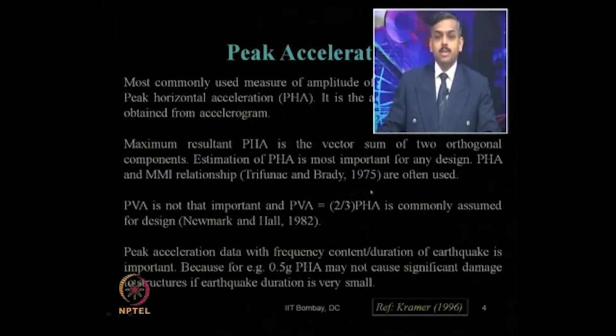And Trifunac and Brady in 1975 proposed for the design the value of PHA with respect to the relationship with the modified Mercalli intensity scale, MMI scale. Generally the PVA is not that important. Earlier people used to think so, as proposed by Newmark and Hall in 1982, but in recent days people say it is better to estimate PVA also, that is peak vertical acceleration. In the absence of PVA data, as per the suggestion by Newmark and Hall 1982, PVA can be considered as 2/3 of the value of PHA for the design purpose.